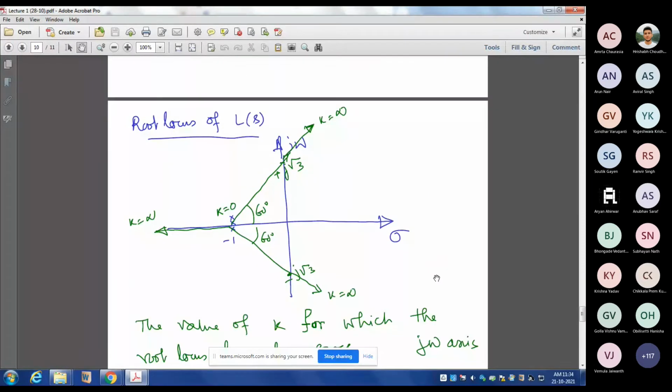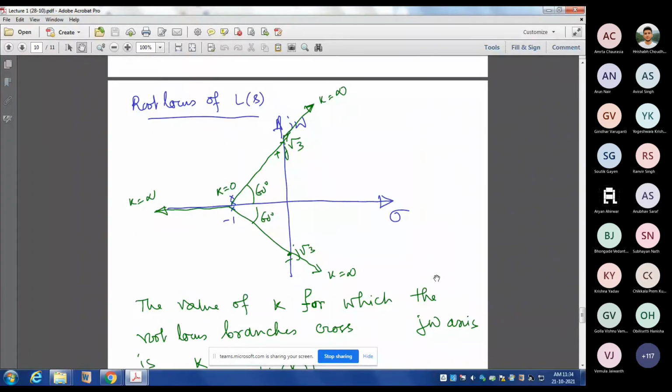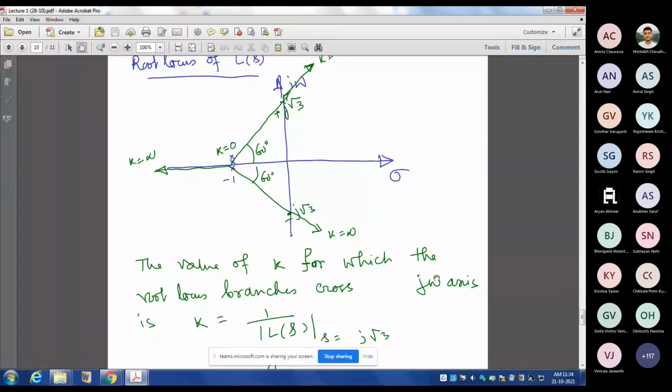Sir, you said that the lower side gain margin will be non-zero only if there is a pole in the right half of the s-plane, right? So if you apply the RH criteria in the first case, for that (s+1) whole cube example, I get an additional condition like K should be greater than -1. Can you explain that?